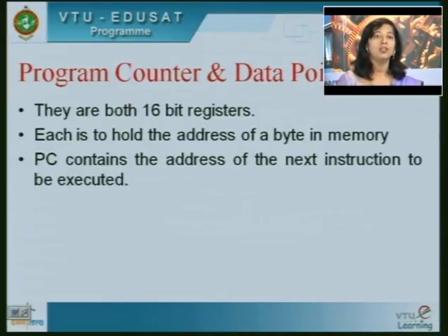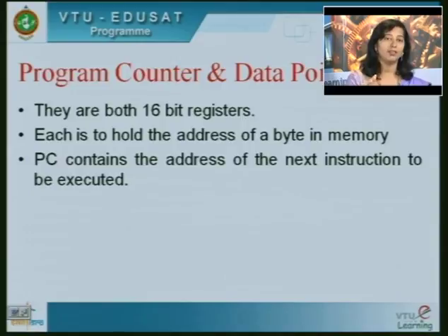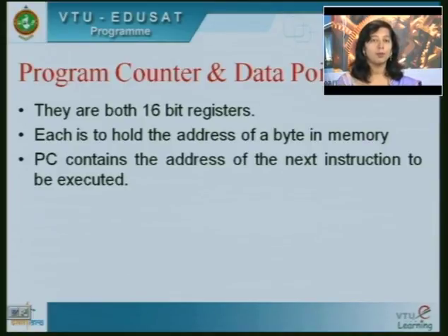You should jump to another instruction and do that. If there is no carry, then you should do the following instruction. So all this can be obtained if the program counter points always to the next instruction which is written in the program memory. So it will always point to the instructions of the program.